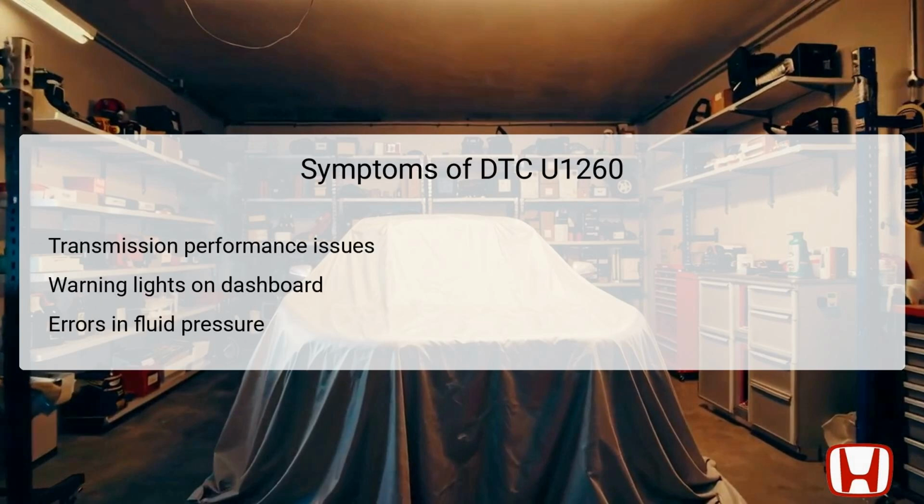When DTC U1260 is triggered, several symptoms may manifest, impacting the driver's experience. One of the most noticeable symptoms is poor transmission performance. The vehicle may experience erratic shifting, delayed engagement, or even potential stalling. Additionally, warning lights may illuminate on the dashboard, alerting the driver to transmission-related concerns. These visual cues indicate that a deeper investigation into the vehicle's systems is necessary. Errors in fluid pressure can also occur, further complicating the vehicle's operation, leading to additional strain on the transmission. Being aware of these symptoms ensures that drivers are more vigilant and can seek timely professional help to avoid further complications.